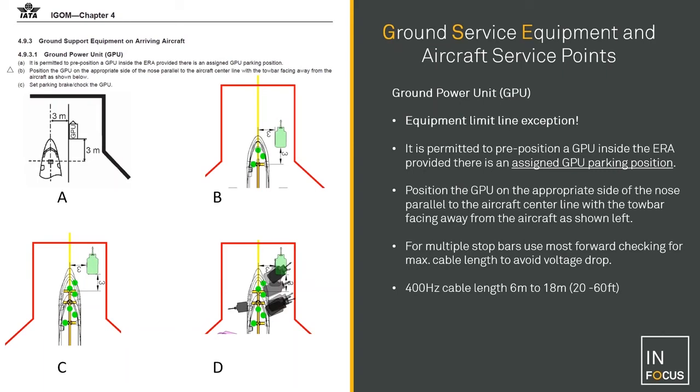It's always important when you do have permanent pre-positioning locations for equipment, as it is in this case, that markings are there. It gives a great sense of security for other people who are working around, especially the pilot arriving in a position. If he sees the vehicles are standing in a marked zone, he knows that things are most probably safe, and he will proceed to move in.